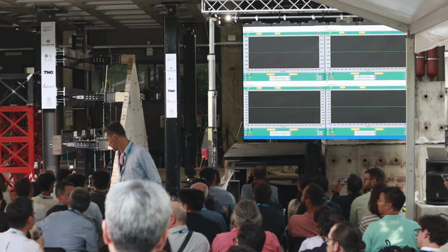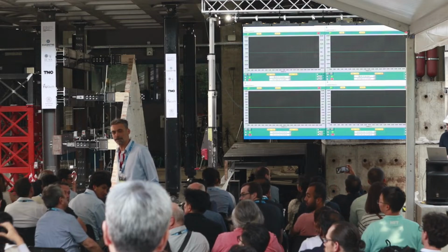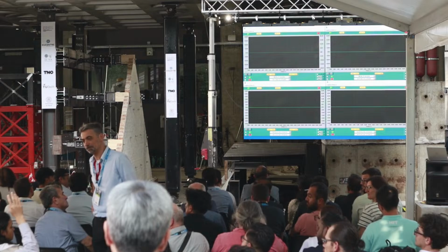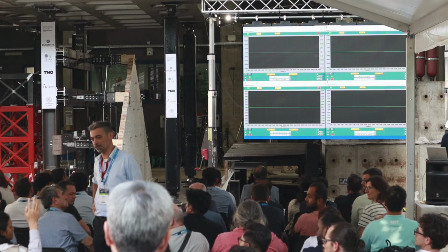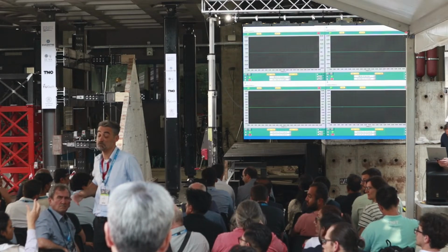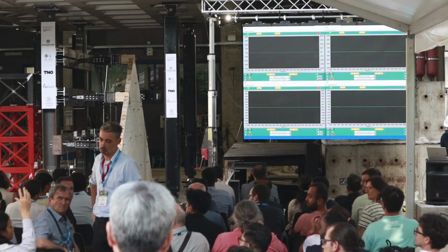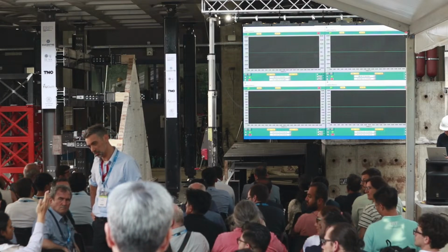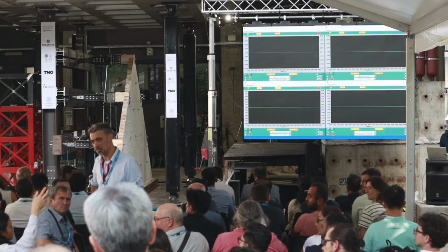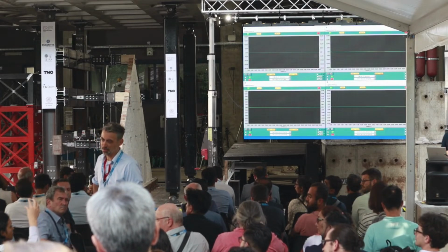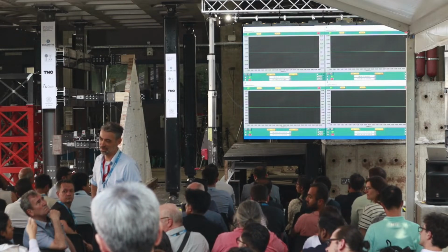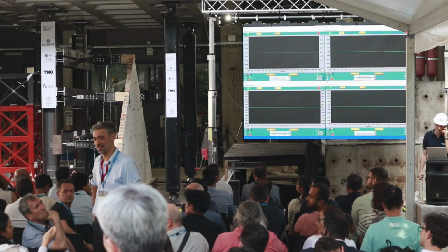Thank you for your presentation. Just one question about how you treat the bells up there. It's very interesting. You have 2 bells up there, they are 340 kilograms in total, and you said that you fix them up there. You mentioned it's like the worst scenario, like an added mass up there. But it looks to me like only one end of the real situation, because in a real situation it will swing, so it will work like a 2 mass damper, something like that. I understand this is a worst scenario, but how far is it from the real situation? Would you say that your result is over conservative in this case? Thank you.